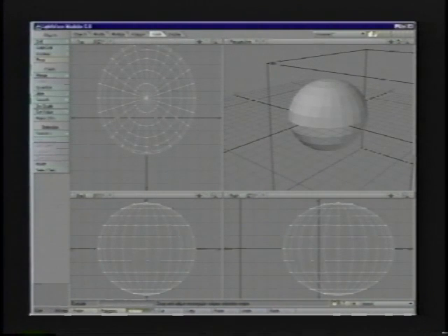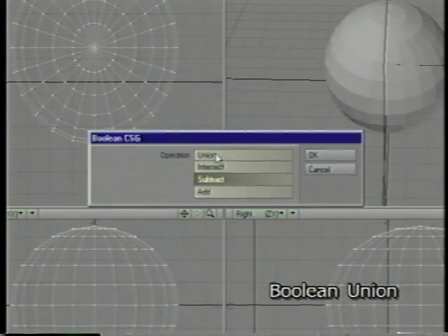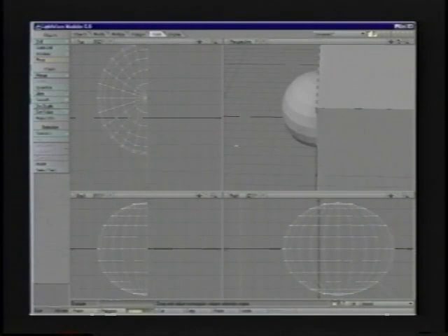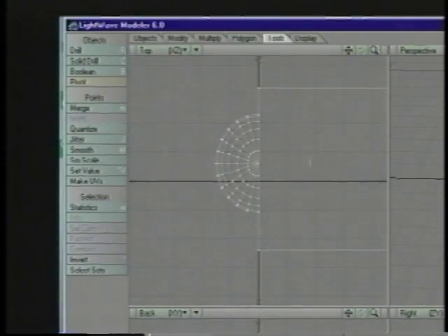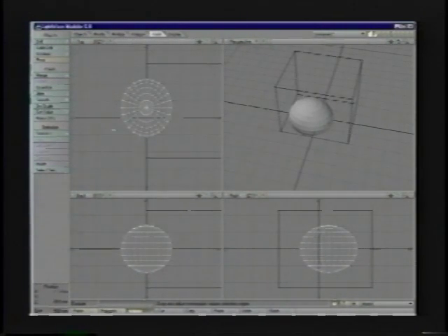single-sided object. And let's take a look at a few of the other Boolean selections. So if we do Shift B and say union and say OK, now you'll see that it adds both pieces of geometry together, but it doesn't keep the section of the ball that was inside the box. It does a union on both of them. They appear to be just sort of smashed into each other, but you'll actually see that when the Boolean happened, the box, as the cutter, cut out the remaining part of my ball in here.